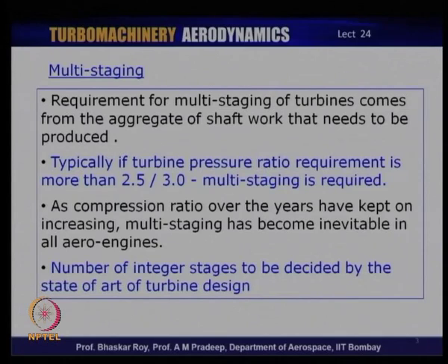Now, to begin with, if the turbine pressure ratio requirement is more than 2.5, and in a modern one a little more than 3, typically multi-staging would be resorted to, because a single stage turbine can give you a pressure ratio or pressure drop of the order of 2.5, and you can probably stretch it to 3. But anything more than that, in a commercial engine, you would need to resort to multi-staging.